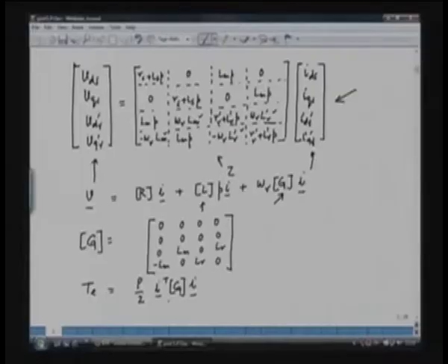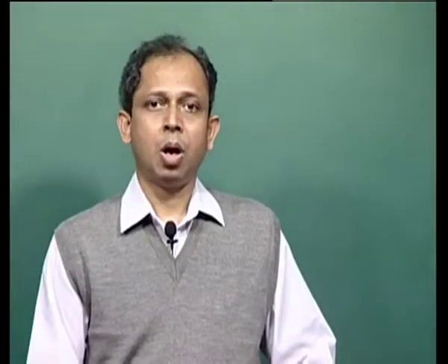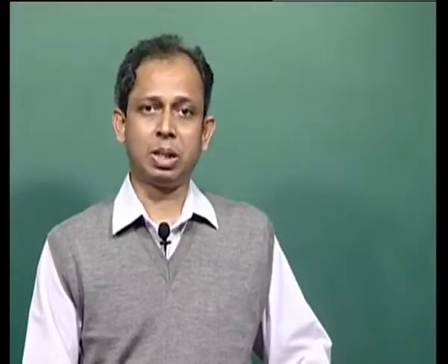And we have already seen that the transformation that we have used, the transformation for the stator and the transformation for the rotor, has got per phase power invariance. So if we have a 3-phase machine, the total power is 3 by 2 times the power of the 2-phase machine, because the per phase power is invariant here.